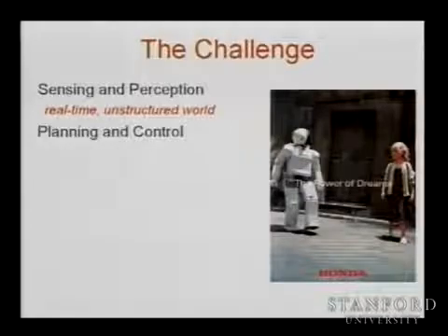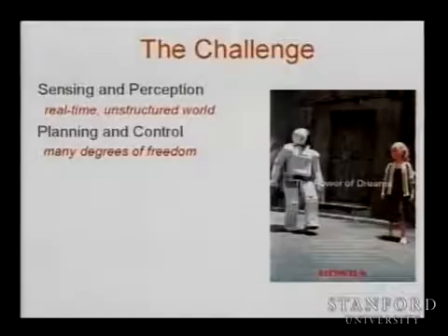Well, in planning, the world is changing all the time. Maybe something else you wanted to mention? Maybe multiple inverse kinematic solutions? Well, the number of degrees of freedom. You have a robot with not 6, 5 anymore. You're talking about many degrees of freedom, and you need to resolve and respond in real time.